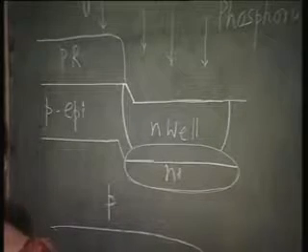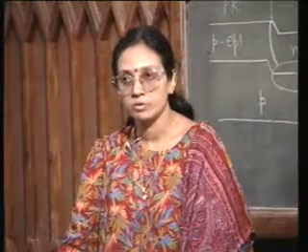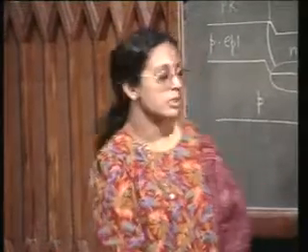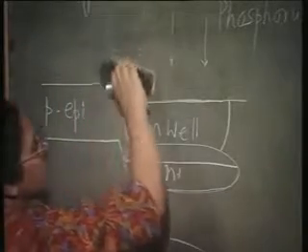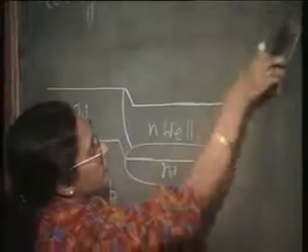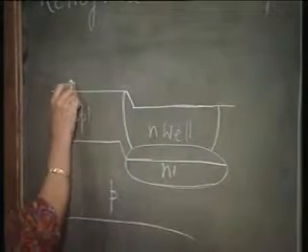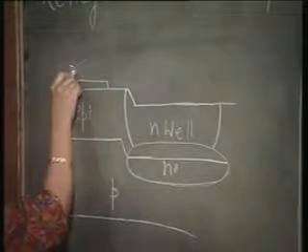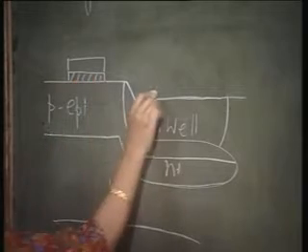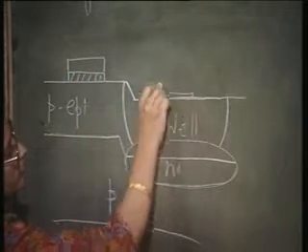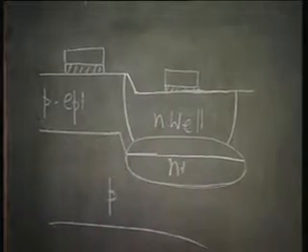Okay, and all you have to do is to form the field oxide before proceeding with the source and drain diffusion. Okay. So, again, after removing this photoresist, this is what you have. Now, you define the active regions by the oxide nitride mask as before. Subject it to oxidation.